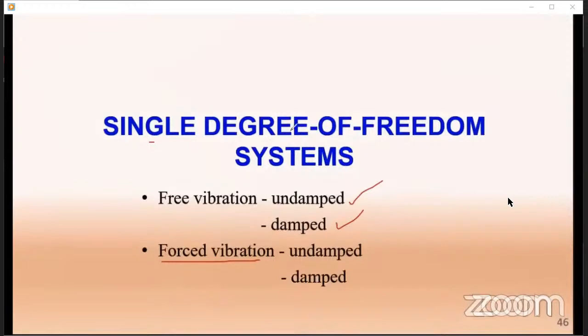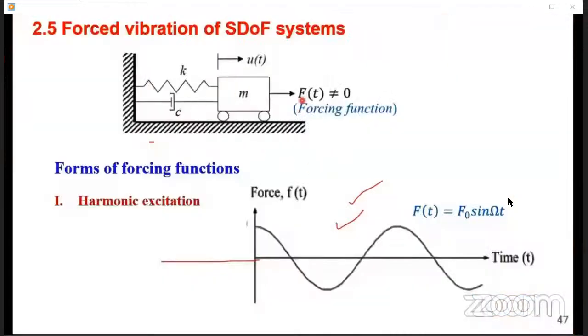And today, that's why we are moving now to the forced vibration. And as you can see, we move to the next slide. Now we are introducing back another part, because our equation of motion, as usual, if you remember, is m times acceleration plus damping times velocity. Remember, for it to be like this, we are talking of viscous damping, plus stiffness times displacement is equal to F(t).